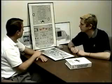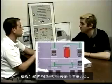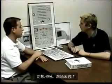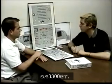Fault lights. Describe to me a fault light in a wing tank pump. A fault light in a wing tank just means that there's low pump pressure. Fuel numbers. Are there some numbers associated, some limitations that you can come up with for the fuel system? Yeah, we've got a new one at United, the fuel imbalance. It's changed to 3,300 pounds.